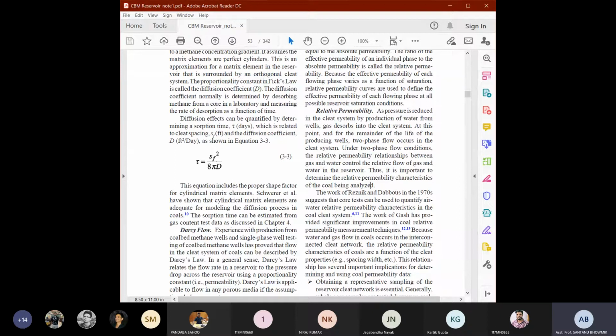It is also the relative permeability between these two phases, because at the border of the water and the oil and gas layer, there will always be some resistance, because of the viscosity or the different properties, and because of the different quantity per second flowing through a channel. So this relative permeability becomes more important whenever there are two or more phases, and that has to be taken into consideration.